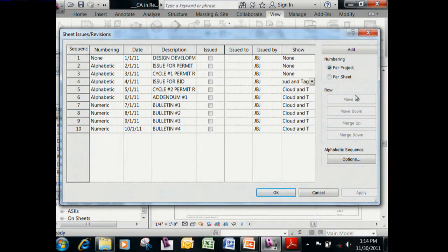And that gets really confusing, and I think you don't want to do it unless you have to, because what that means is if you make a change relating to one area and it's going to show up as the first change on that sheet, it'll be number 1. But if you're making that same change on another sheet, but there have been other changes there, it may be number 6. So it doesn't coordinate anymore and gets kind of confusing.